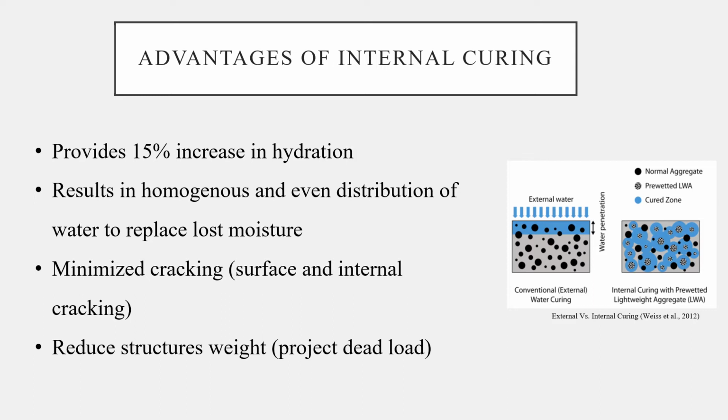Currently, curing is mainly introduced to concrete by applying an outside source, adding water to the outside surface of concrete, which is okay in compensating the water loss due to evaporation. However, for external curing, only the top strata of the concrete surface is nourished with water. The rest of the concrete, or the concrete at depth, is not cured.